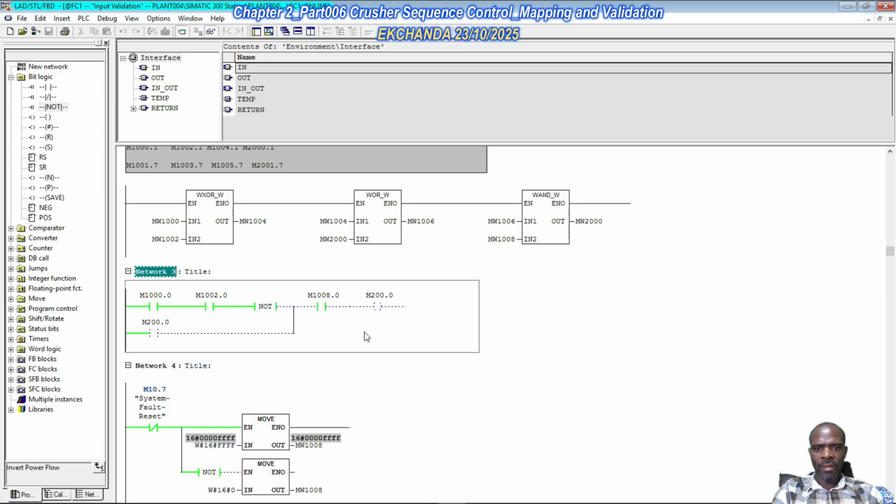Okay, we have something like the system is reset. But if this bit became false at any one time, so modify to 0, then you'd have this address becoming true. And then this would actually represent a faulted state, or it would monitor the behavior of this system.